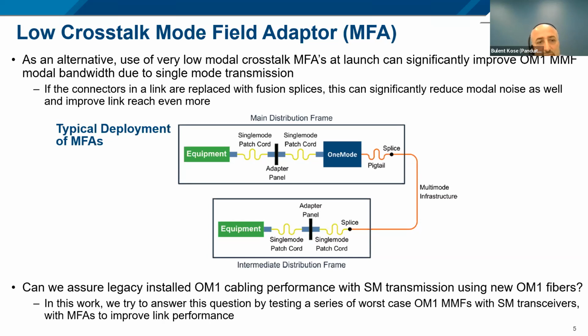So the idea is, can we assure legacy installed OM1 cable performance with single mode transmission using OM1 fibers? That's the question that we're raising. In this work, we try to answer this question by testing a series of worst case OM1 multimode fibers with single mode transceivers with mode field adapters to improve the link performance.